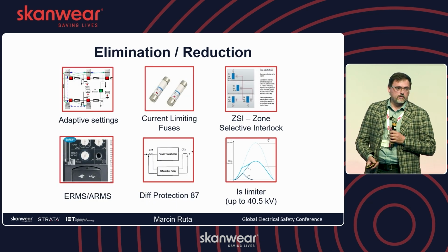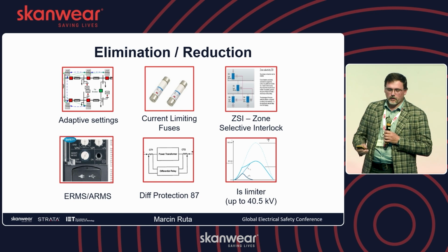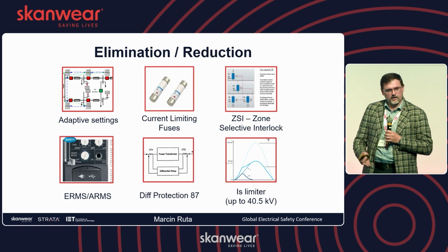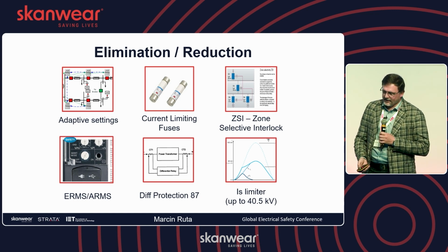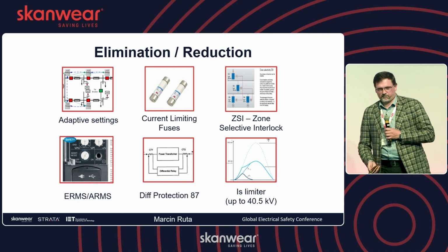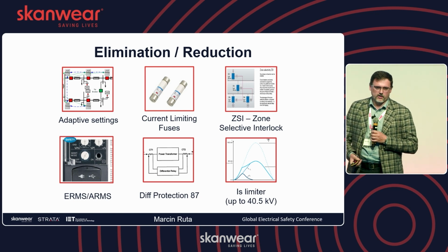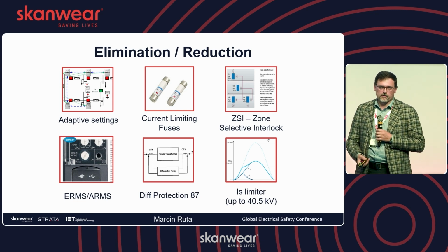Adaptive settings, very rare to see, actually. But a very interesting thing, current limiting fuses. Generally, most current fuses are current limiting, which is not a rule of thumb, but a very interesting thing to have. Zone selective interlocks, communication-based protection. A very useful thing when you run out of time for protection coordination.